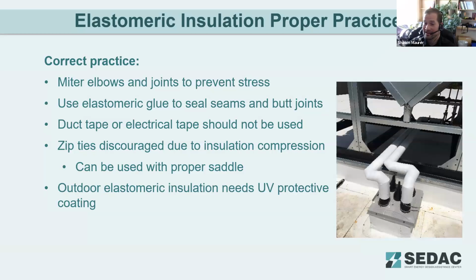Something else to make note of, again, here, sometimes we see electrical tape or duct tape used to seal joints and hold this insulation together. Adhesive tapes are not allowed. Again, it can delaminate and then you don't have the tape there holding those joints together, providing protection. Or if you're doing maintenance and you have to pull that tape off, you can damage the insulation and require more cost to replace it.